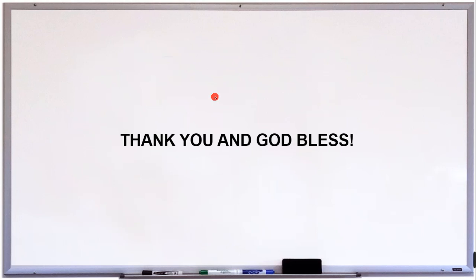But then again, if the problem requires you to solve for the internal forces like the tension, you may split the multi-body system into individual systems, and you can still apply the work and energy equation right there.